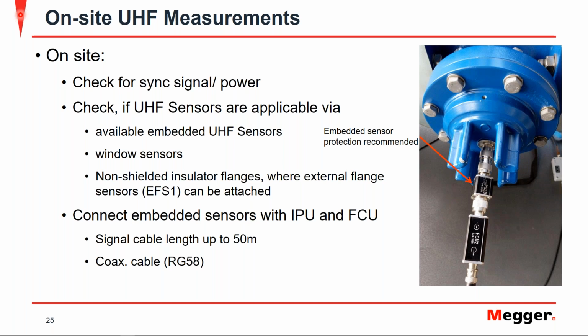Next, you want to check to see if your UHF sensors are applicable, which ones you have that are applicable. So do you have any embedded sensors? Do you have window sensors? Do you have external flanges that are non-shielded where you can use the external flange sensors?